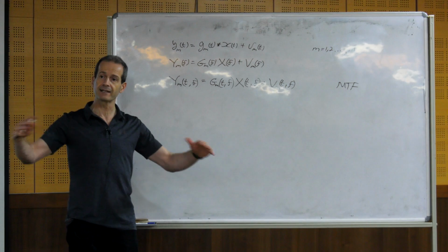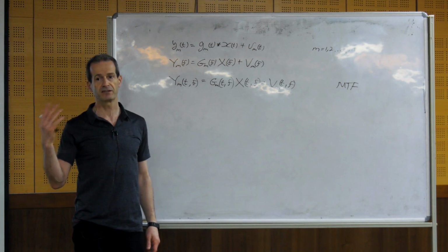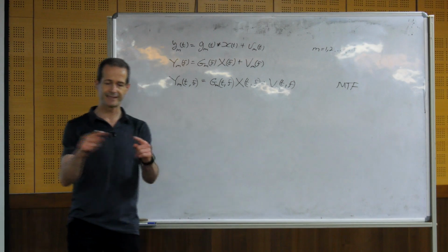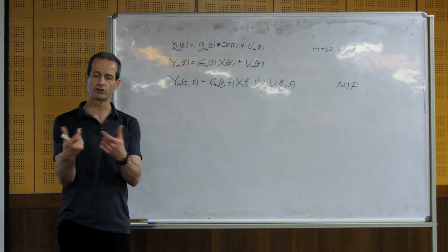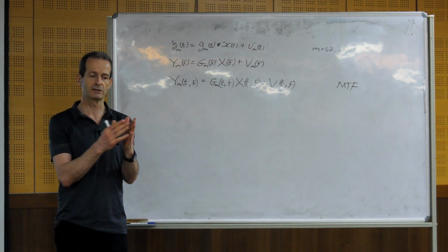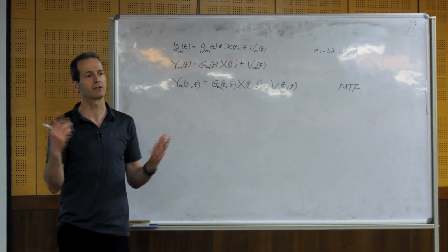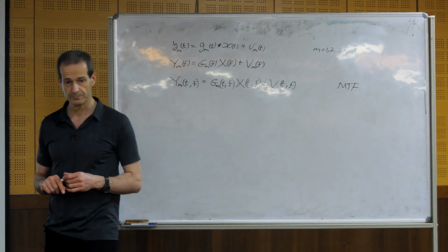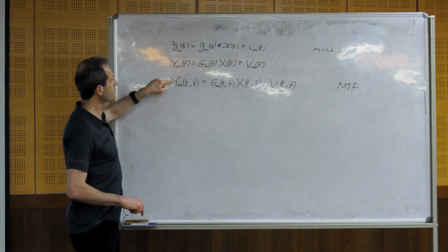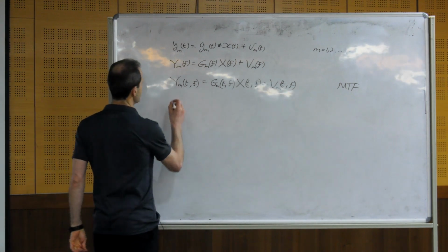Of course, we can take a longer window of the STFT, but this has a very big disadvantage, because then during that window we cannot discriminate or identify different phonemes or different parts of the speech, because during that window the signal is non-stationary, it is changing during hundreds of milliseconds. So what do we do? Instead of coming from here to here, we need to do something else.